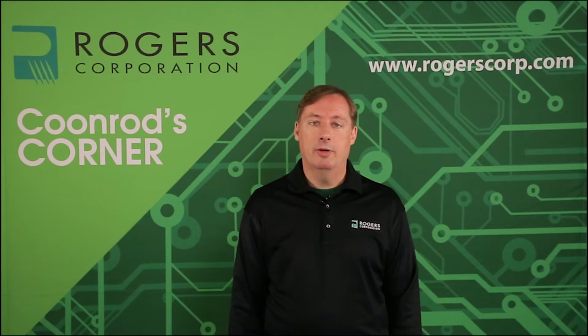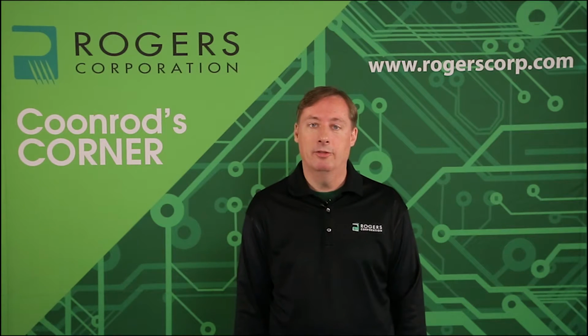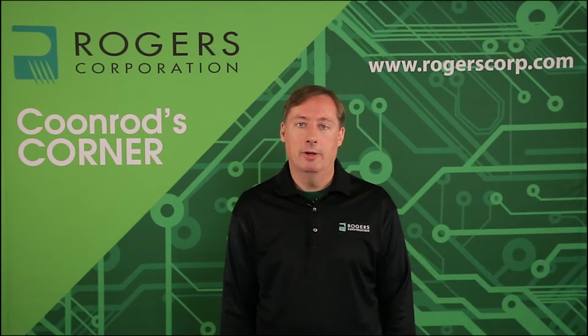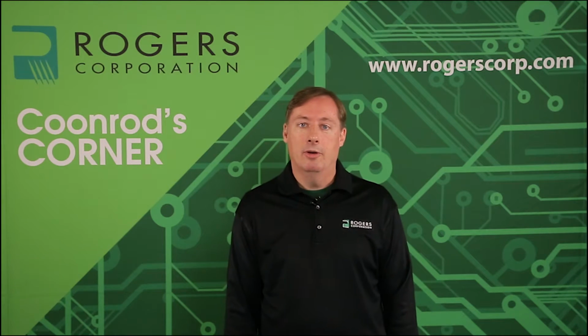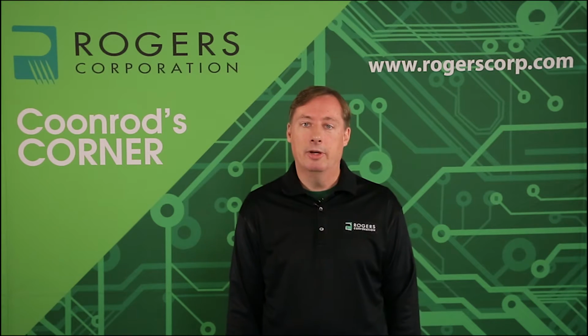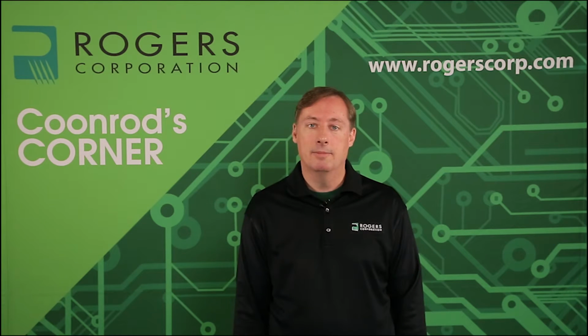The PCB substrates that are used in the industry really are not that good a thermal conductor, even though they're behaving functionally as a thermal conductor to transfer heat from the signal plane to the ground plane. If you actually look at the numbers for thermal conductivity, they're typically around 0.2 or 0.3 watts per meter Kelvin. And that's really not that good. Considering copper is about 400, most of our substrates are considered as thermal insulators, but they have to act like a thermal conductor. So in some cases, we have formulated our materials to have increased thermal conductivity, and typically, as a rule of thumb, when a material has a thermal conductivity of 0.5 watt per meter K or greater, that's considered very good thermal conductivity.